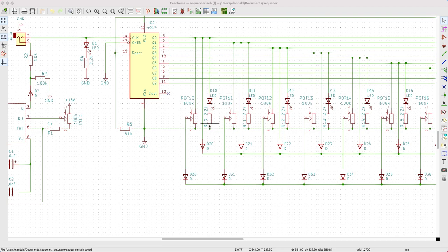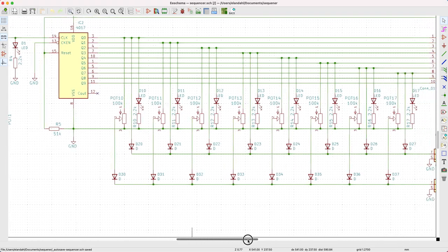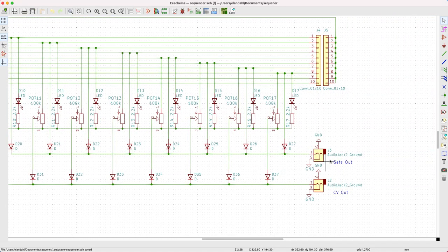This second line just simply has a diode coming out. So this really is the raw output of this decade counter. And the raw output goes through another diode that, again, just prevents feedback to other parts of the circuit. And they are all linked together. And all 8 of them are chained up to come out on what's called a gate out.